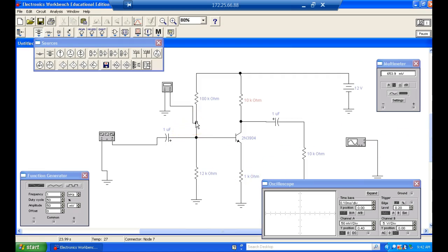Move up here. What are we going to measure up here at the collector? 0. Notice we get some weird stuff coupling through. 100 millivolts, right? We've lost the reverse bias, so we're getting a little leakage through that diode right there. Are we okay? And what should we see down here? Should see 0.6 of a volt less than what we had there, so we'll see what we measured there. See what happened? Everybody okay? Makes sense? Good call. Most people miss the beta.